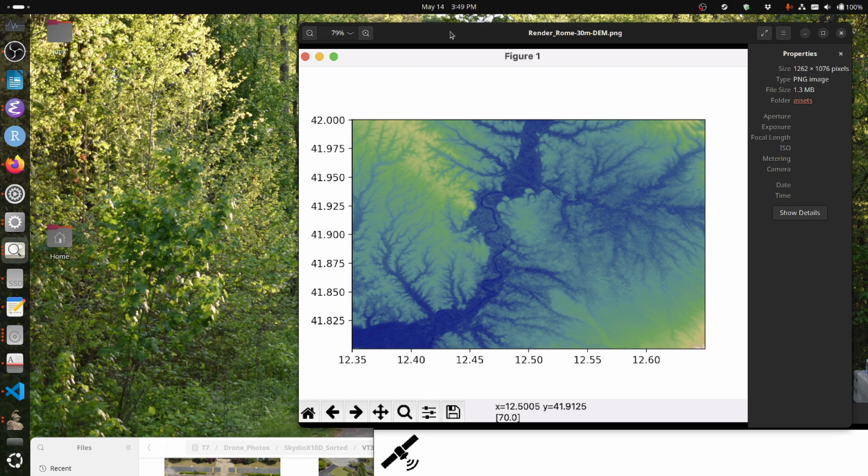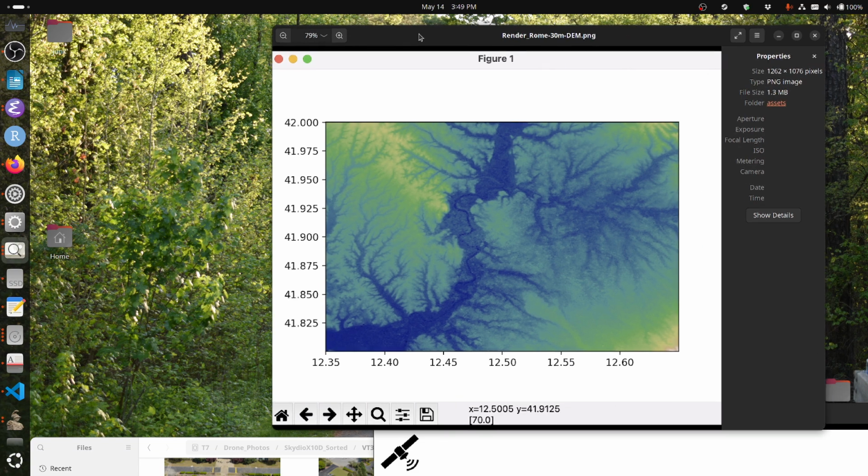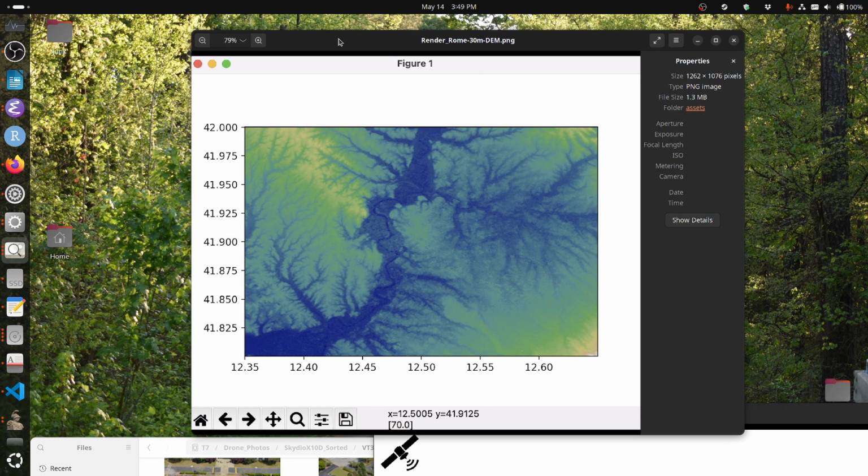Internally, OpenAthena automatically selects the best available terrain file for the area surrounding the drone and interpolates between these data points as it simulates that line out from the drone camera's position, orientation, and pixel within the image until it intersects with that ground terrain. Because we interpolate this data, the accuracy is often far superior than the 30 meter or 10 meter horizontal resolution would imply.